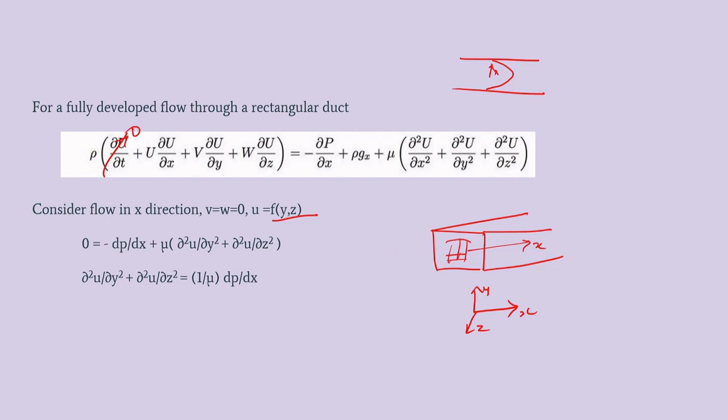Okay. So till it is fully developed, as you have seen in the circular cross-section pipe, the velocity profile will be in a rectangular shape at first. It will be gradually attaining the shape of a parabola. Once it is fully developed, it won't be changing with respect to the x direction. So for a fully developed flow, u is a function of y and z only.